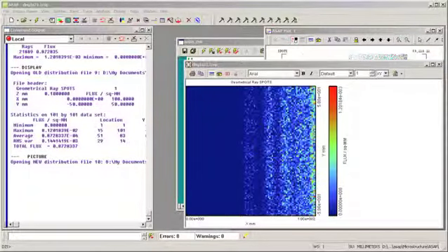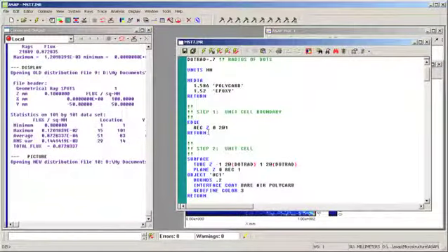It is 4 simple steps. First, we tell ASAP the dimensions of the unit cell. We do this by defining a rectangular edge with the same dimensions as the unit cell as shown here. Here's my edge. It's a rectangular edge with a semi-diameter of 1 unit or 1 millimeter.